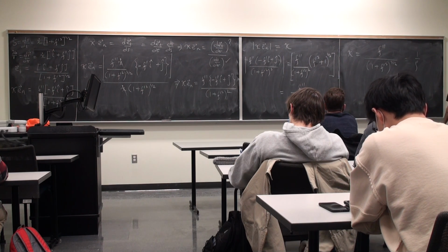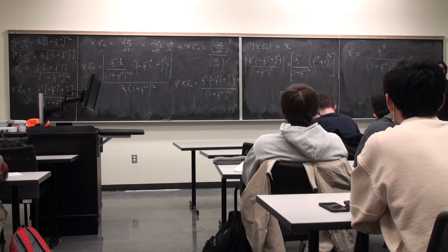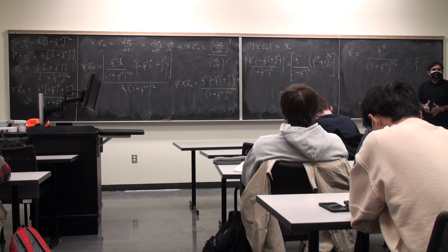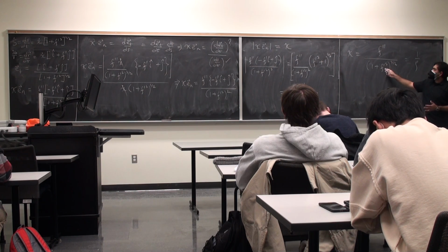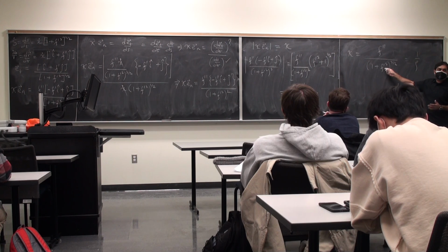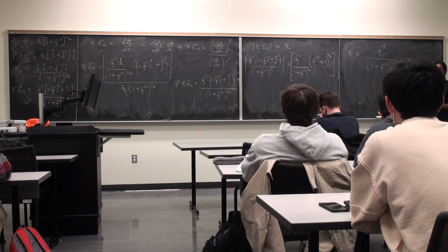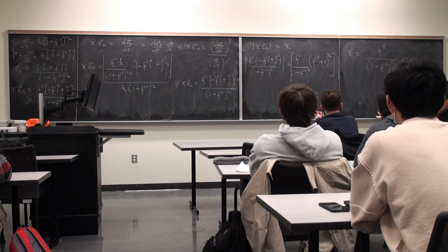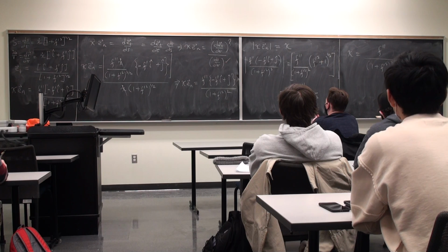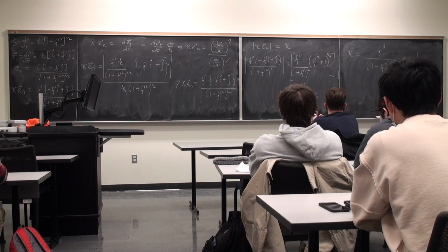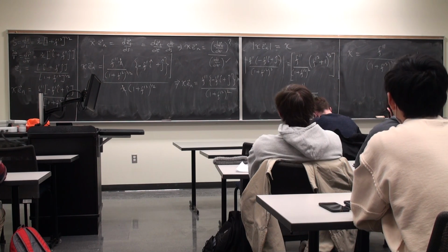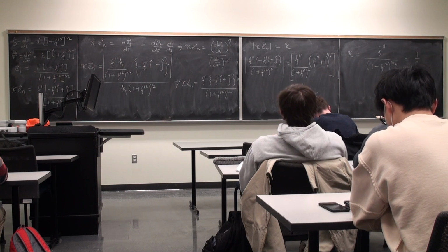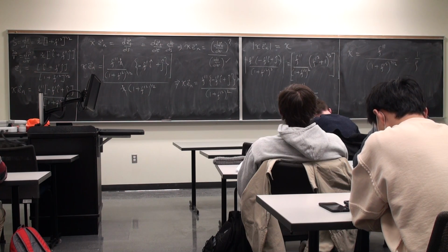Typically in strength of materials, you will assume that this df by dx is very small, so this quantity is ignored, so that your curvature is just the second derivative of the planar curve. That's your starting point typically in beam bending problems. Okay? So this is a very common formula. In a way, we have actually derived the curvature of a planar curve.